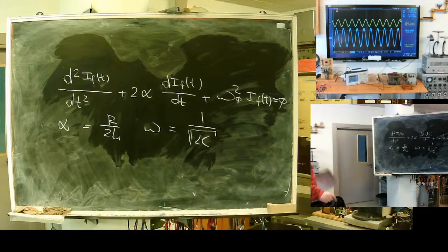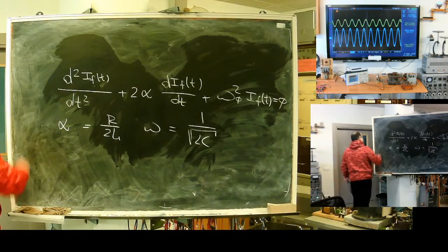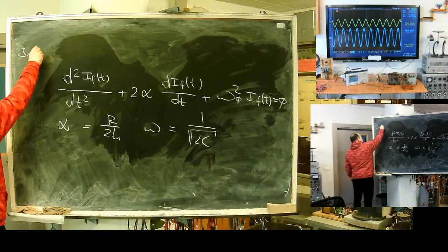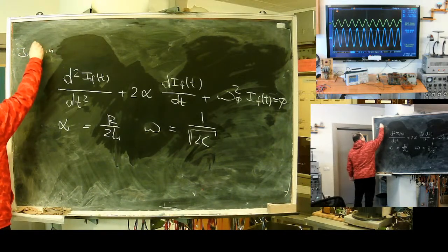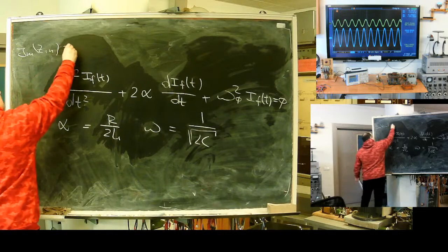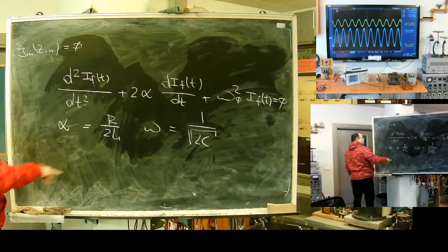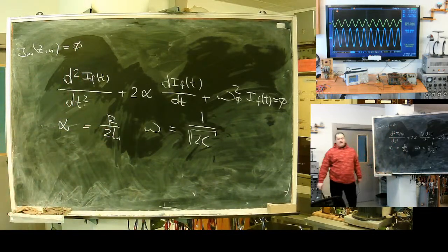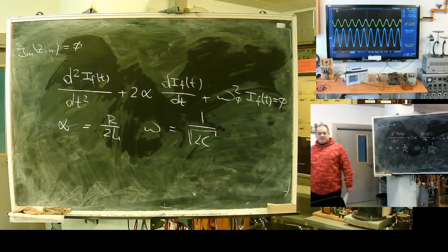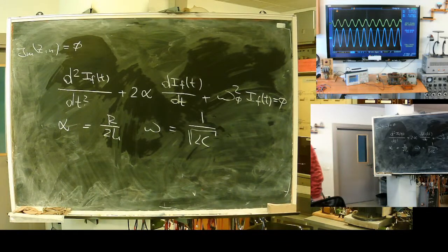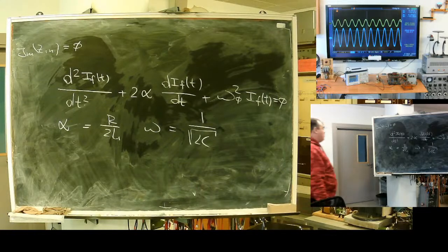Actually, it's an oscillation frequency. If you set the imaginary part of the input resistance equal to 0, you will get the same frequency at which the capacitor reactance is fully compensated by the coil inductance when they are equal.